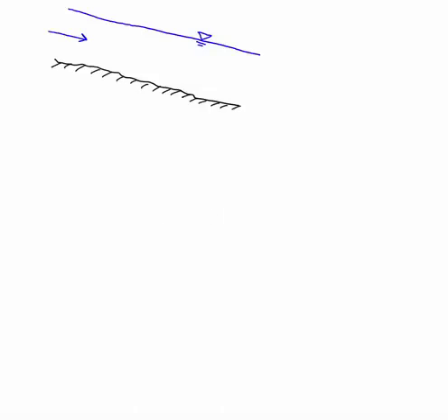I want to go over that derivation for boundary shear stress that we did in class the other day. So here is a drawing of kind of a cross-section view through a river. This is the bed of the river. This is the water surface here that has some slope to it. If there wasn't a slope, the river wouldn't flow. And it slopes at some angle alpha, okay? Or some slope, rise over run.